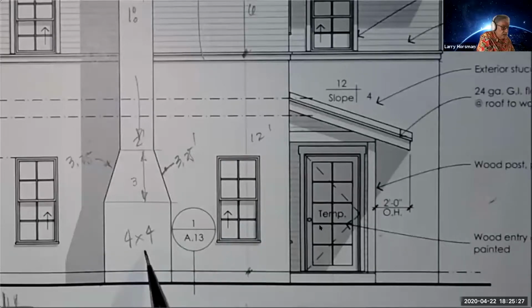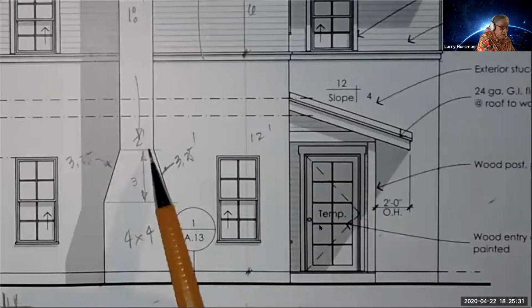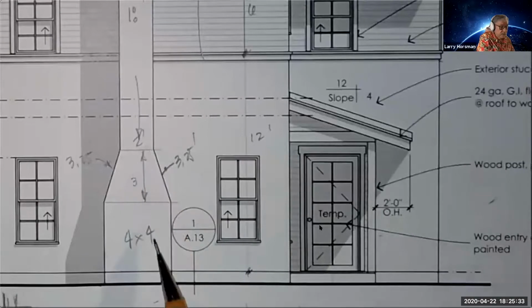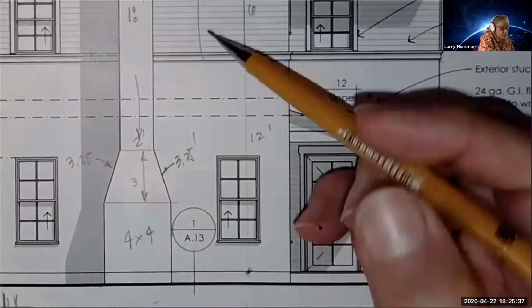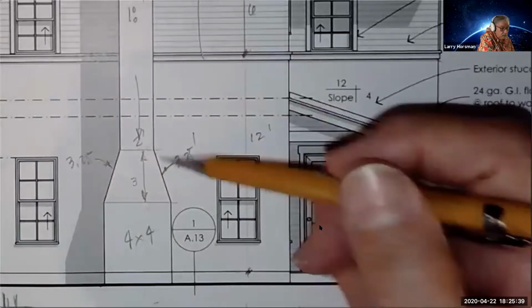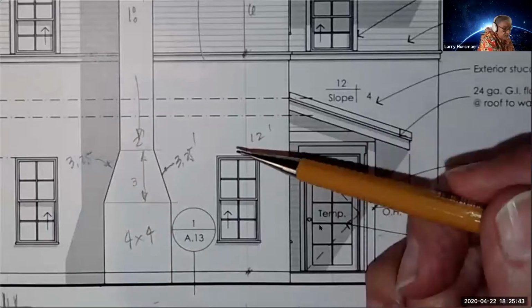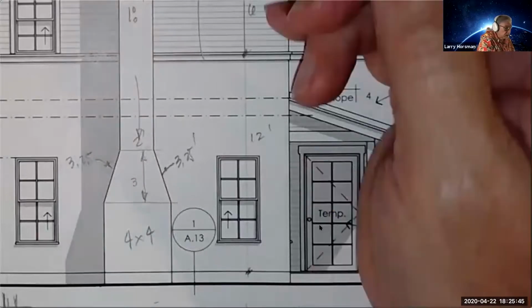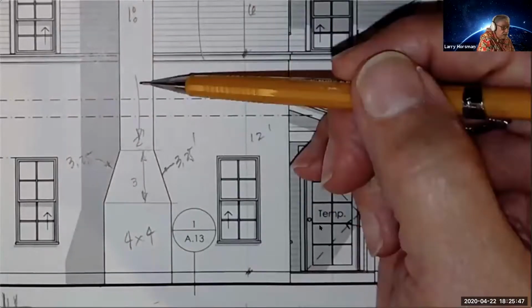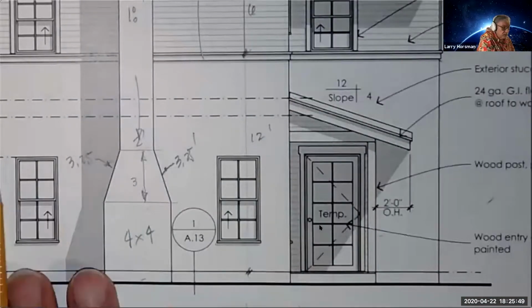This, I just take the 4 feet and the 2 feet, take the average, which would be 3 feet times 3 feet. So that's about a yard. I've got the little sides here, so a lot of times these get missed. They're a little bit longer, not a big deal. But again, you're going to need scaffolding once you get up to about here in order to put this stucco on.